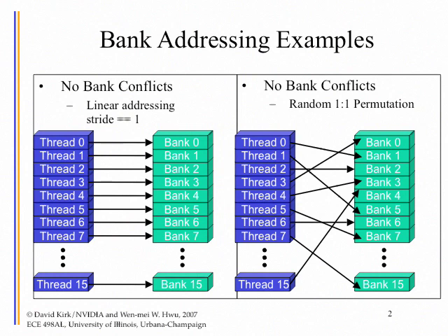Okay? So that's great. But even in some situations, such as FFT, for example, you will be accessing things across each other, and you're not doing strictly just sequential access. However, as long as the mapping pattern is such that each of you would eventually end up in a different bank, no matter how complex or how simple these mappings are, you will be able to all get your data in one clock cycle.